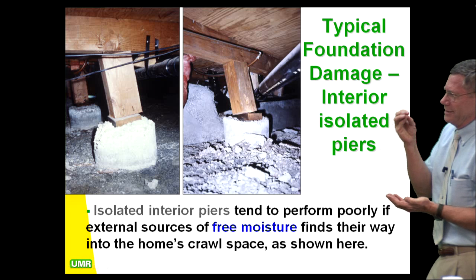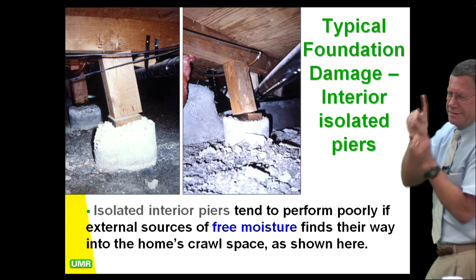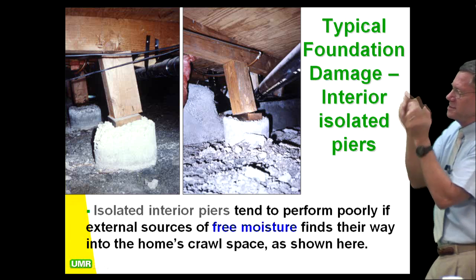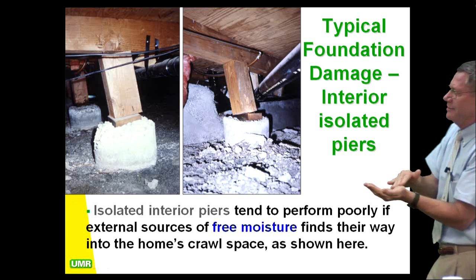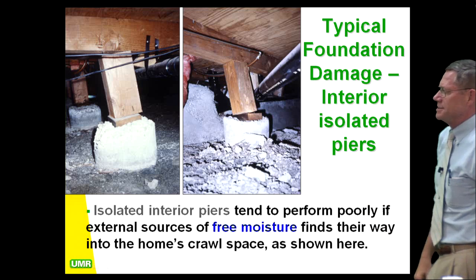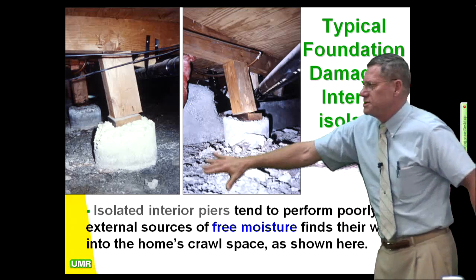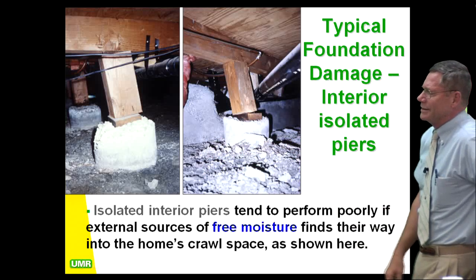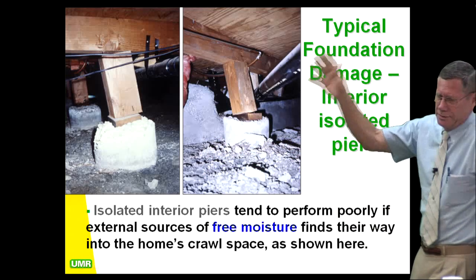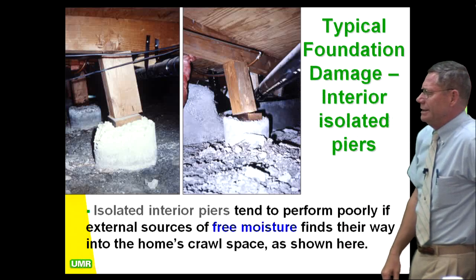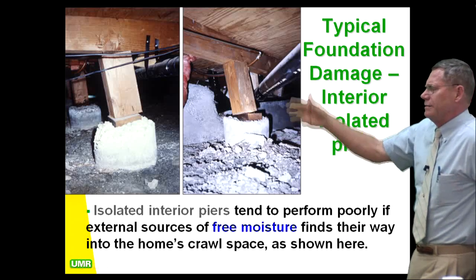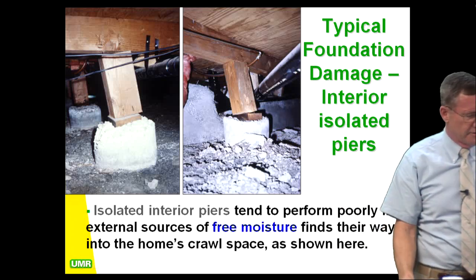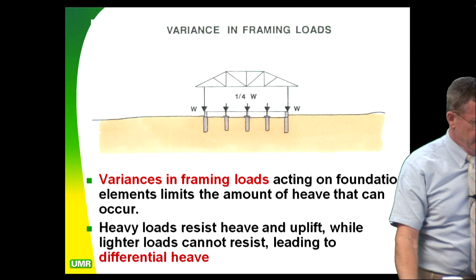They look like little tiny, pretty little popcorn things with all these little needles sticking out, and you put them in your hand, and they melt in your hand, at about 94 degrees. And so these salts are real typical of over-consolidated shales in dry areas because you don't have enough water there to wash all the salts out of the system. So you actually can have sulfate attack in extreme cases against the concrete. You have to have type 3C concrete if you have sulfates in the soils.